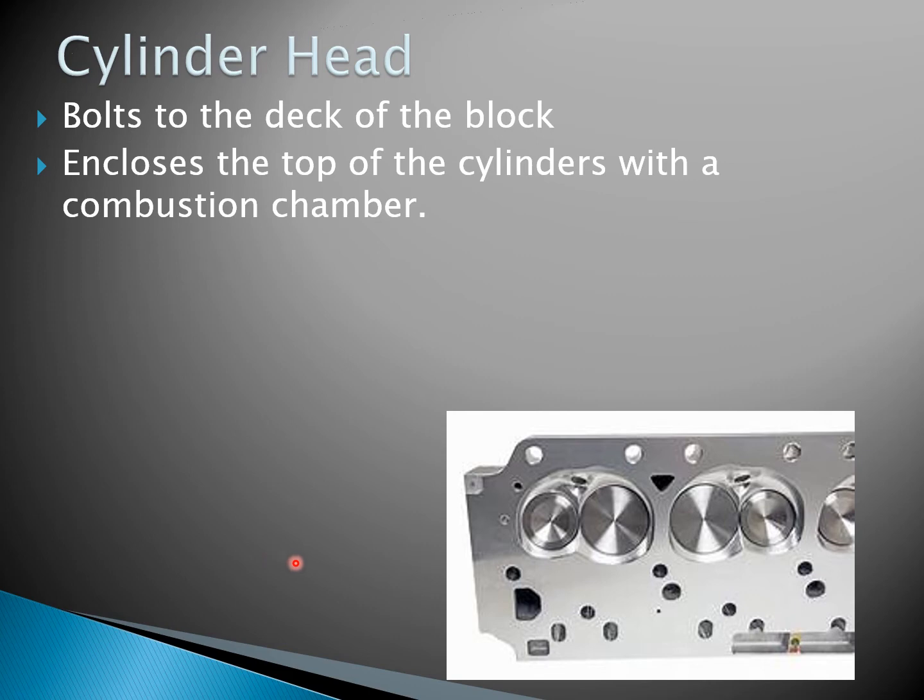Now, I'll point out on this, each cylinder, so one cylinder is going to be right here and so on down the line like that. And this particular head has two valves. They always have a minimum of two valves. You're going to have an intake valve and an exhaust valve. You notice though, these valves are not the same size. So which one do you think is bigger? And there are only two answers. It can either be the intake valve or the exhaust valve.